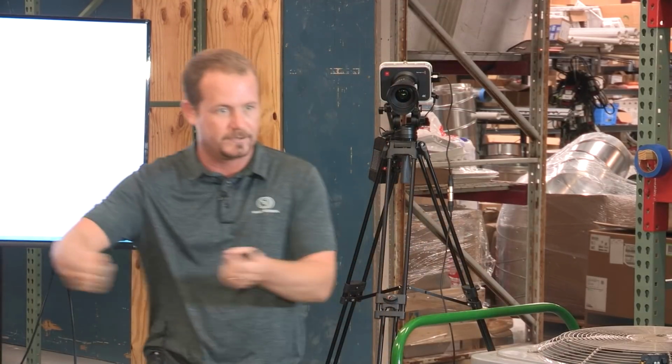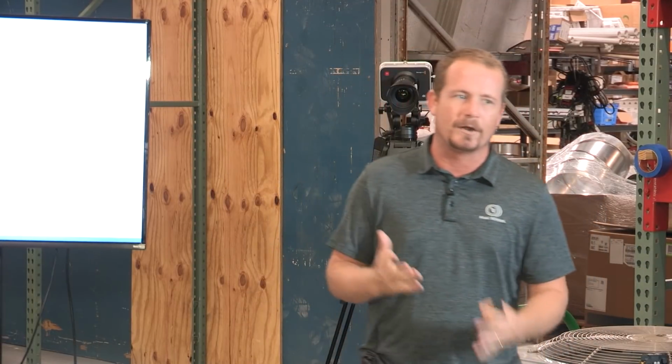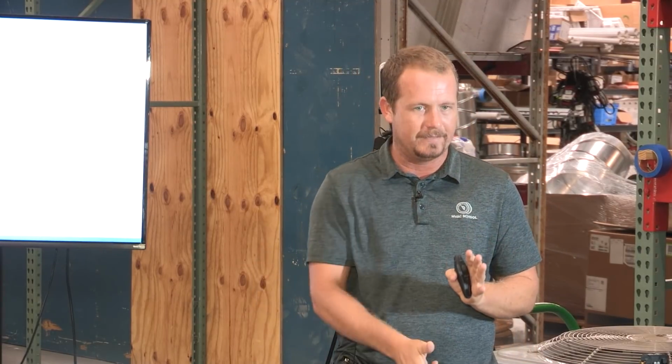So thermal imaging is great when you're in a rack house with a bunch of compressors that are running, and you can look at the differences in temperature and the differences in their connection point temperatures, because you're comparing them to each other. Looking at the absolute readout on a thermal imaging camera is the same as an infrared. They're not super accurate as an absolute temperature readout, but they're very helpful when comparing things against each other.